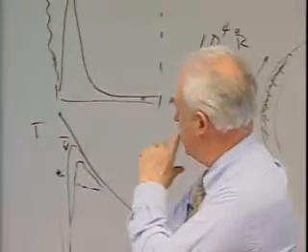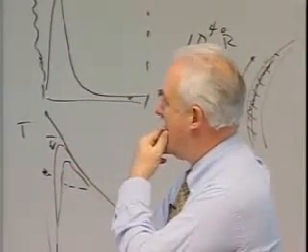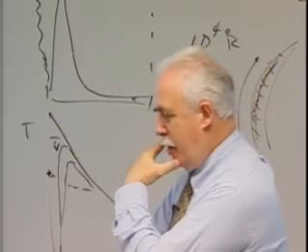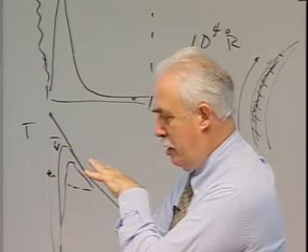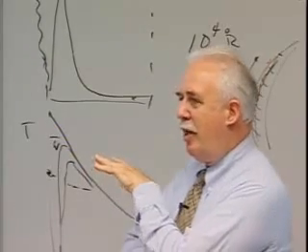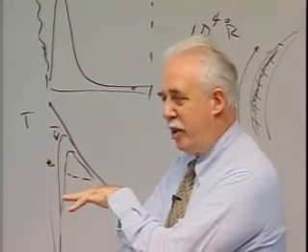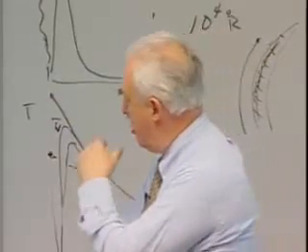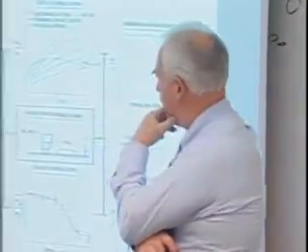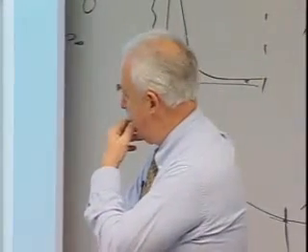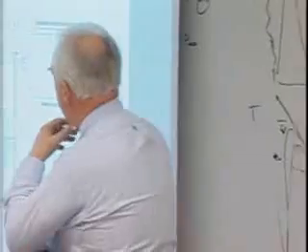Okay. Boundary layer transition. I talked about the boundary between the turbulent and laminar heating. Characteristically, at the shuttle level, your heating goes up by about a factor of 3. If you go to higher Reynolds numbers, it can get significantly higher. So you want to avoid that factor of 3. Our initial estimate on the effective roughness, I have to say, was not as good as it should have been, but the technology wasn't really there.